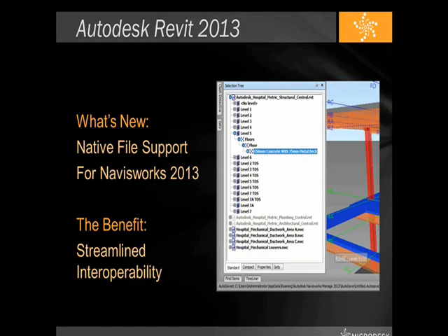Now, because they have incorporated the Revit hierarchy into Navisworks, they have also utilized the ability to select objects in Navisworks by level, family type, object, and material, straight from the selection tree in Navisworks. These functions alone will save you time and headaches when trying to coordinate between multiple models and disciplines, allowing you more organization and less time thinking about how you need to organize the model before it goes into Navisworks for a clash detective.